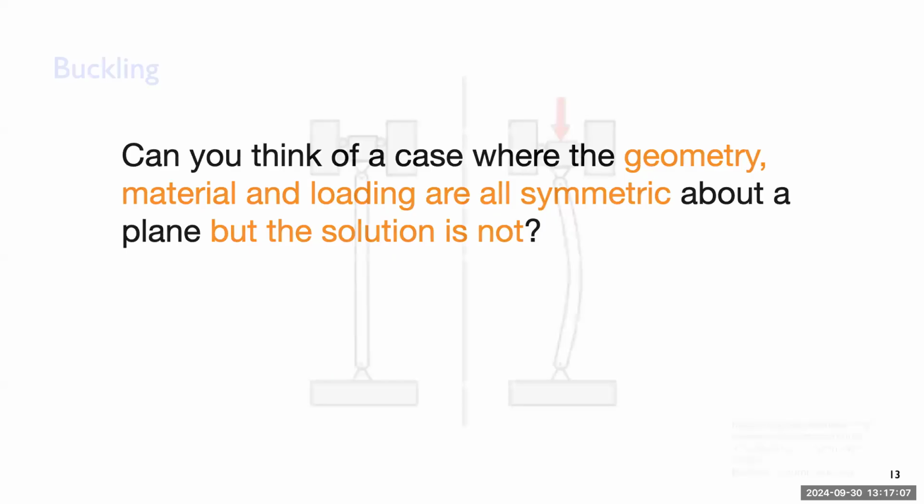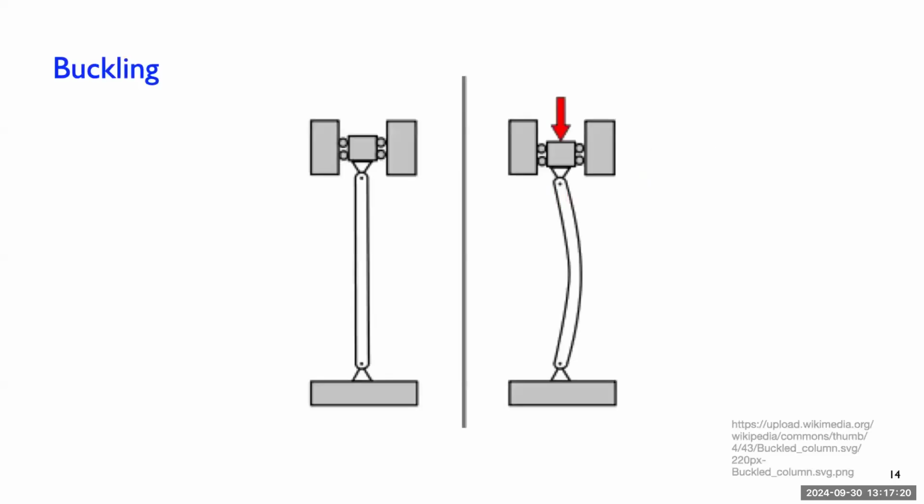If you do another example, if I have a pencil and click down on it, in any direction of equal solution, it will buckle in one direction, and it will buckle just based on round off error. So if you make a mesh and one of the triangles is a little bit bigger on the other side, then that'll be just enough to break the symmetry, and it'll click one direction based on your mesh. And that might be computer specific or mesh specific or precision specific.